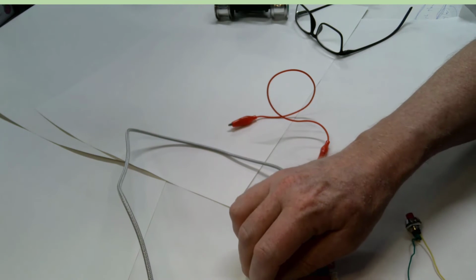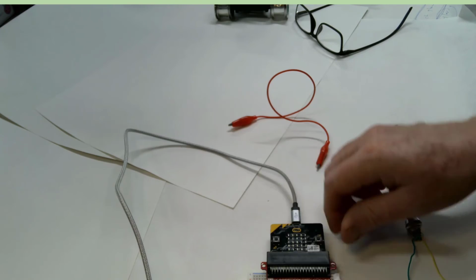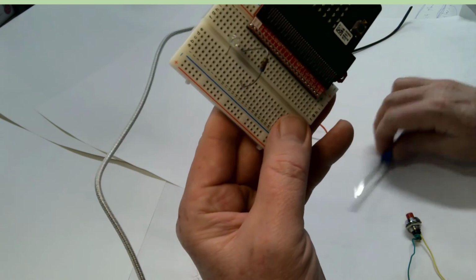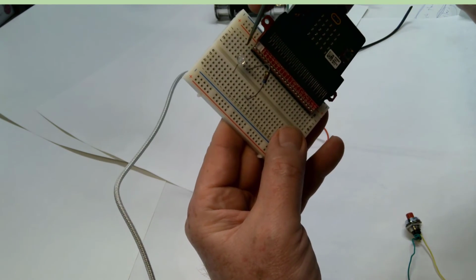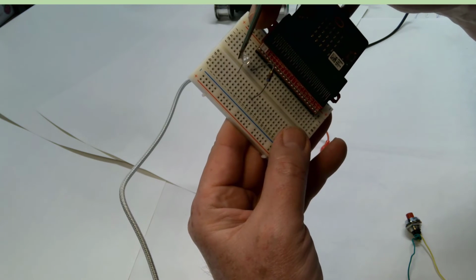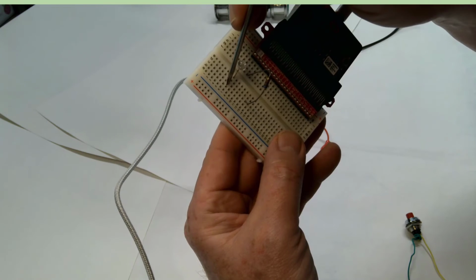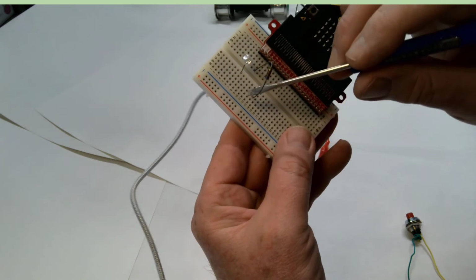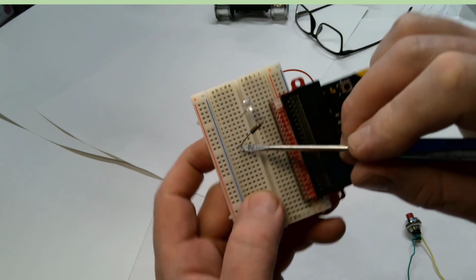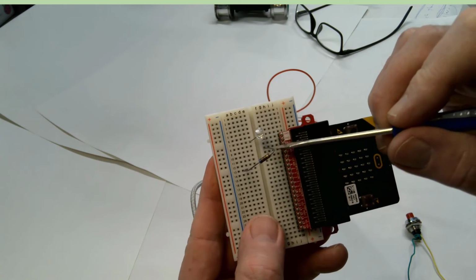I'm going to pull out one of these wires, and now electricity cannot flow through this circuit because electricity flows from this ground pin through the LED into these pins right here that are all electrically connected, but there's no connection to the place where this resistor plugs into the breadboard and then comes back to the 3-volt power source.